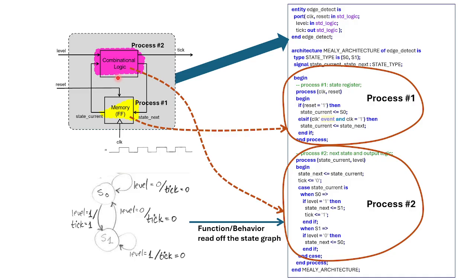So it's very important to keep in the back burner that these two processes emulate and reflect hardware that implements these two processes coexisting inside the FPGA. This is something that we prototype inside the FPGA and do work at the same time all the time. So as a result of this block diagram that pretty much any Mealy finite state machine boils down to, it is best to use this two process coding style in VHDL to describe that.